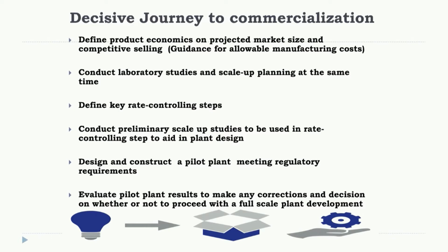Define key rate controlling steps. Conduct preliminary scale-up study to be used in rate controlling step to aid in plant design. Very necessary so that we don't have that much expenditure on plant before we have that scale-up product with us. Design and construct a pilot plant meeting regulatory requirements. Evaluate pilot plant results to make any correction and decision on whether or not to proceed with the full-scale plant.